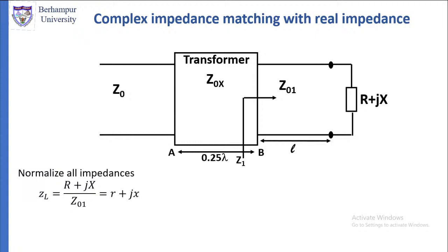It will be a complex number, and then we will have a characteristic impedance which is complex. That again is difficult. Usually the characteristic impedance of a transmission line is taken to be real. The imaginary part is always neglected, as it is negligibly small.